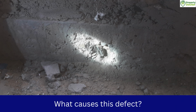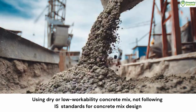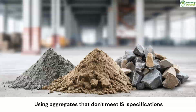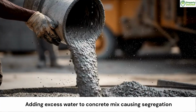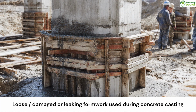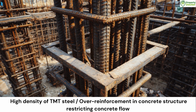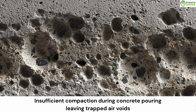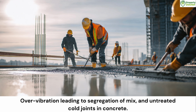What causes this defect? Several factors contribute to formation of honeycomb in concrete surfaces, which include using dry or low-workability concrete mix, not following IS standards for concrete mix design, using aggregates that don't meet IS specifications, adding excess water to concrete mix causing segregation, loose or damaged or leaking formwork used during concrete casting, high density of TMT steel or over-reinforcement in concrete structure restricting concrete flow, dropping concrete from excessive height during pouring, insufficient compaction during concrete pouring leaving trapped air voids, over-vibration leading to segregation of mix, and untreated cold joints in concrete.